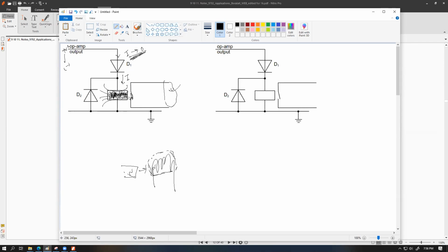So this coil will try to maintain this current within itself, and this will happen only as long as the current keeps falling from I to 0. This is a very small period of time, but within it, depending on the number of turns of the coil, the coil can produce a momentary high EMF, which will try to maintain this current downwards. So essentially this coil will try to pull a very large current through this.